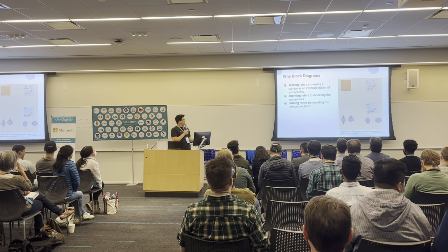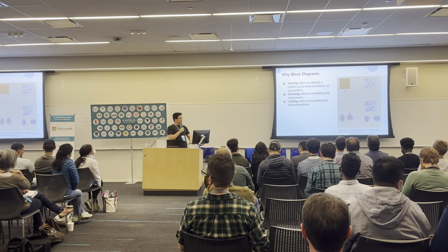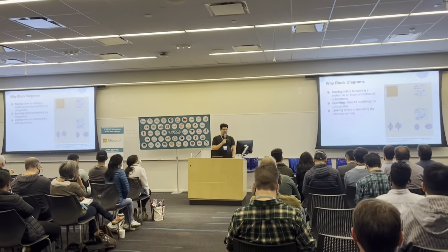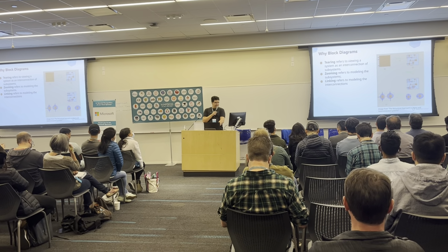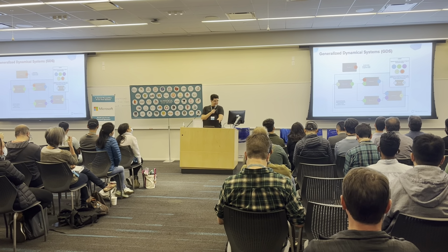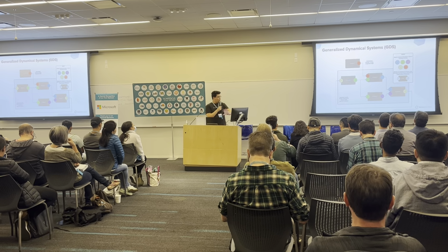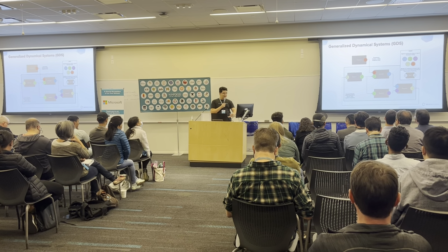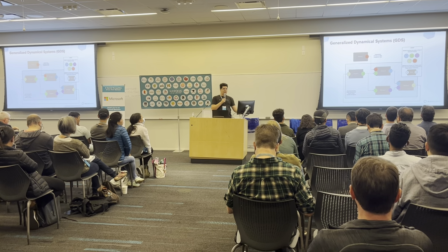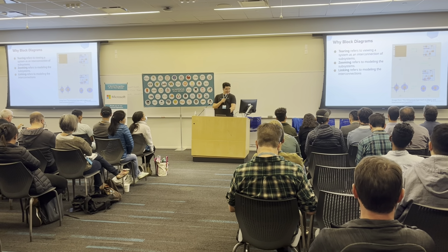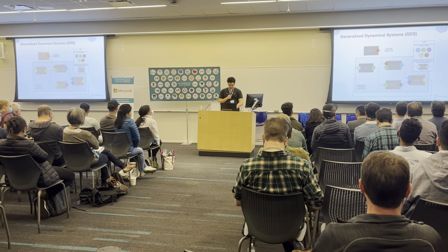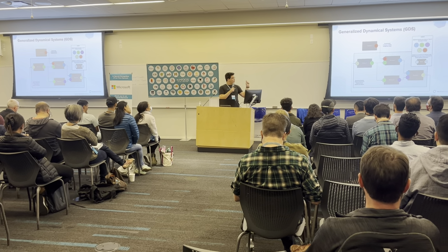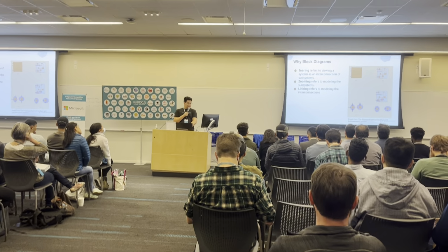All of that goes back to three small concepts. The first one is tearing. If I look at this diagram, I can look at the whole diagram as just one big block or one big logic, or I can tear this one big logic into its small constituents, the small gray boxes. That is the process of tearing.